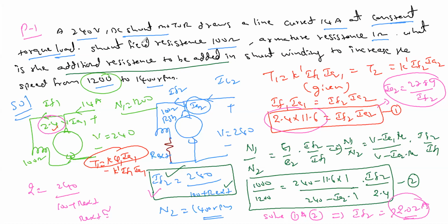You have to take not this much, 0.1 is too much reduction, so don't take that. You should take nearer to the value you have, 2.1, closer to 1.9, that is around 2. So R external will be around 17 ohms, 17 or 18, something like that, right?